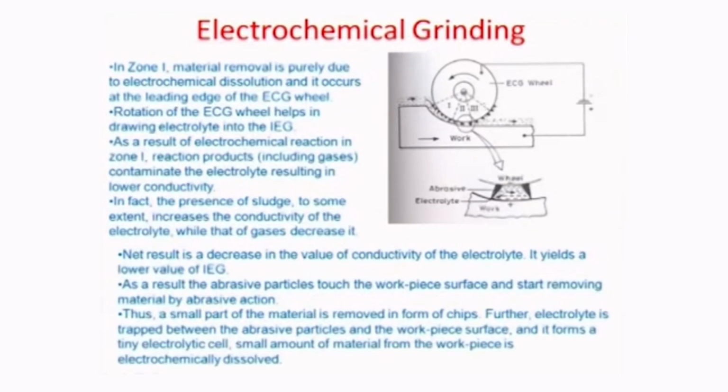As I already illustrated before, electrochemical grinding is a combination of electrochemical dissolution and mechanical removal of material. There is a 90-10 combination: 90% of the material gets removed by the ECM process and 10% by mechanical abrasion. So there has to be some parity between these zones and these different aspects of the ECM, and we will see that zone by zone.